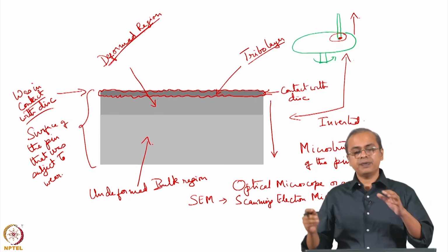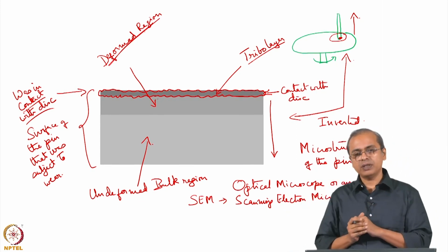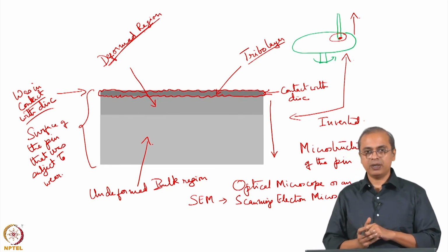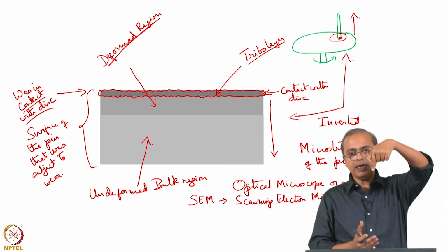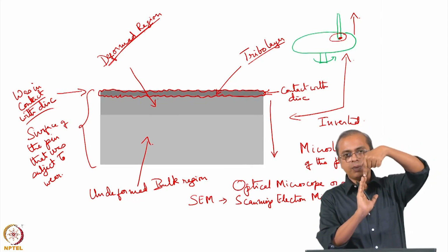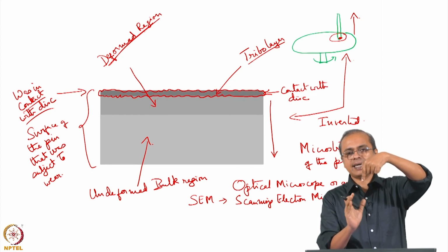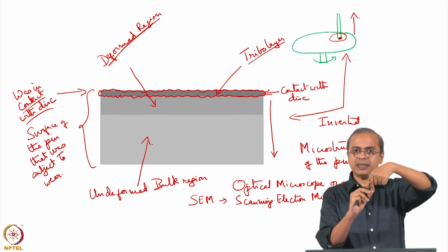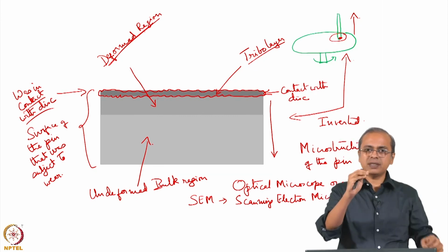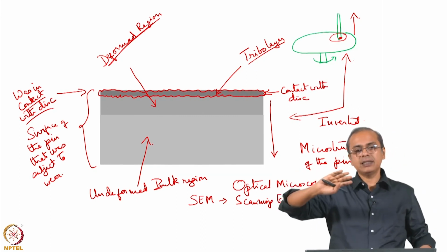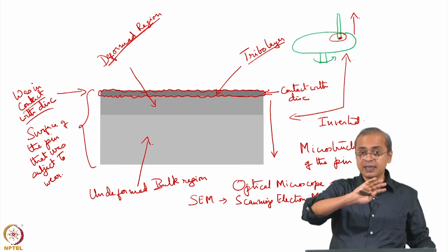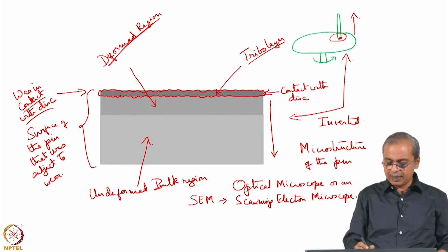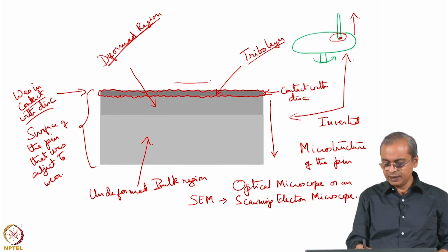and that is because of the mechanical stresses that are there on the pin, because it is being subject to this test of pin on disc. So as you can imagine, with the pin down and as the disc is rotating, you are trying to push the material in one direction, okay. So it is getting pushed tangentially. So the surface layer of the pin is getting damaged, the layer just above that surface is also getting pulled in the direction in which that disc is rotating. So let us assume that the disc was rotating in that direction, right.